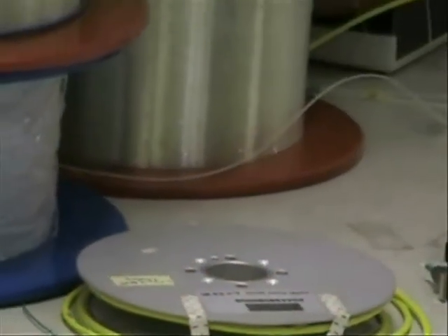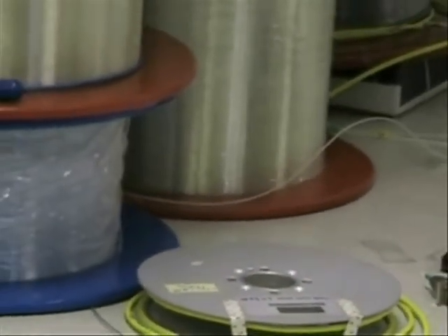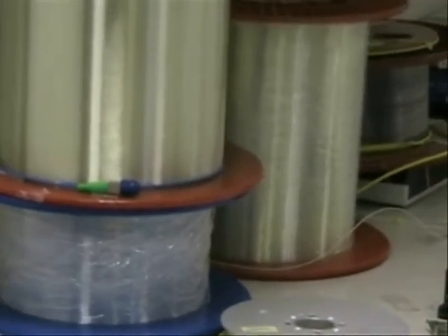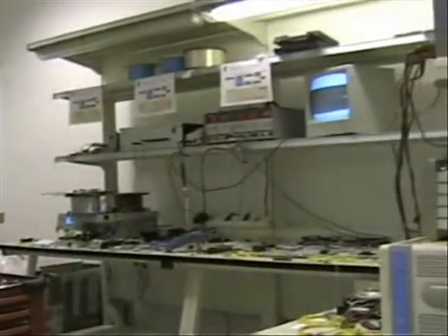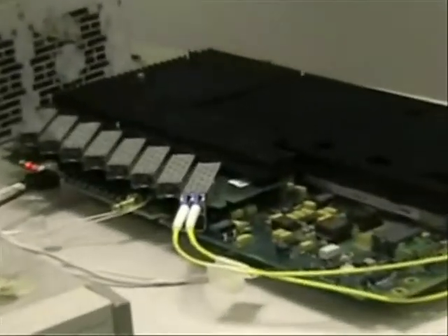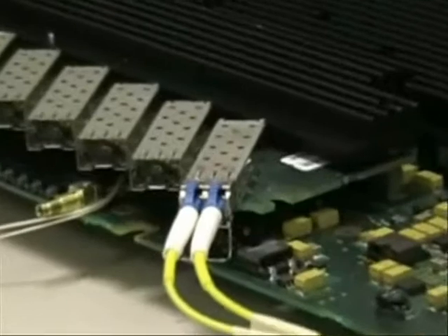In this experiment, we have been able to transmit the 100 gigabit per second Ethernet traffic over a 1.4 km long span of dispersion-shifted fiber, which corresponds to a total chromatic dispersion of 0.9 picosecond per nanometer. The main limitation has been represented by the high jitter of the clock used in the Ericsson Muxponder to generate the 10 gigabit per second Ethernet signal, and by the absence of the clock recovery in the OTDM demultiplexer.